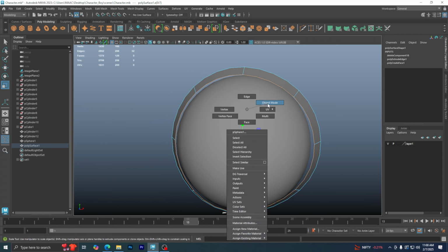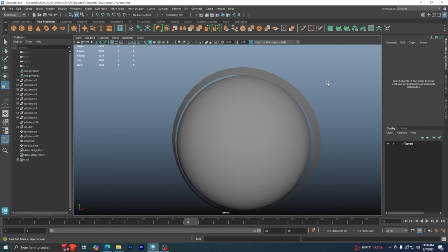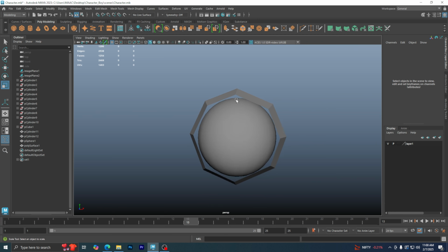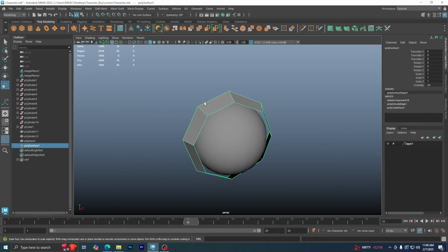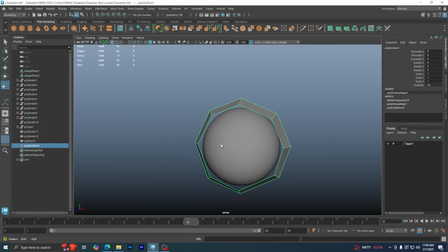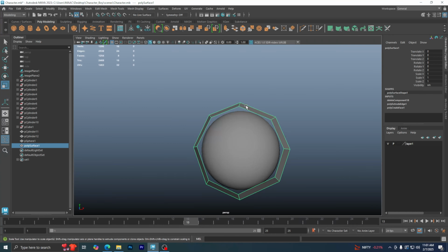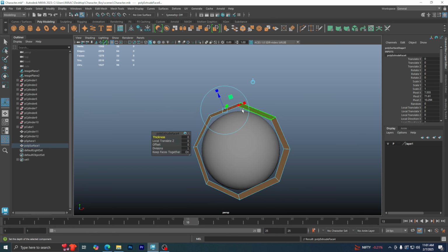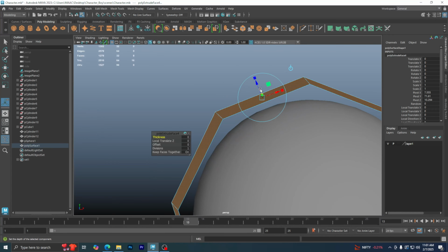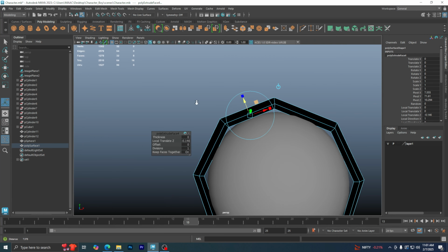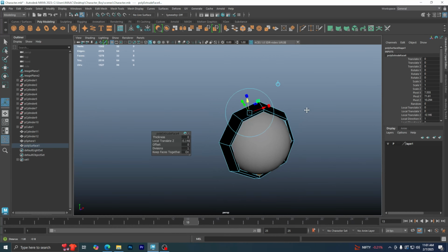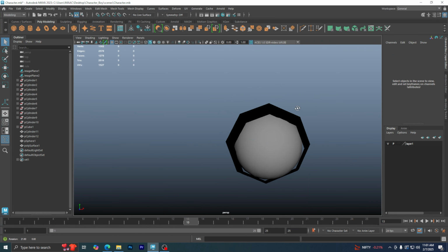So again come out of that and go to object mode, and selecting this you can press 1. Now I want to extrude this overall skin, so press Ctrl+E and then extrude it. Selecting this Z axis, bring it inside in this way, and then go to object mode again.